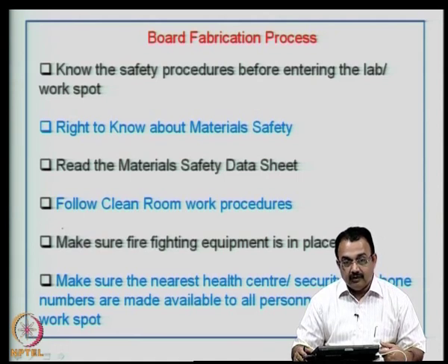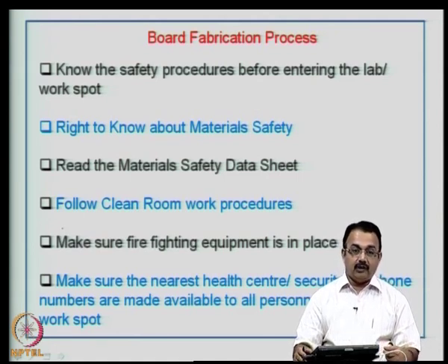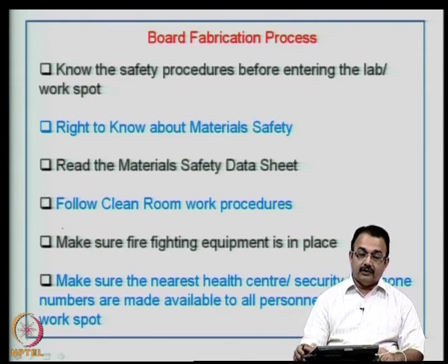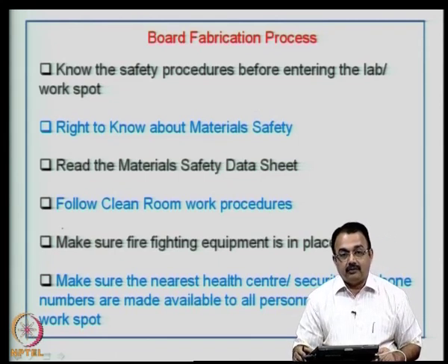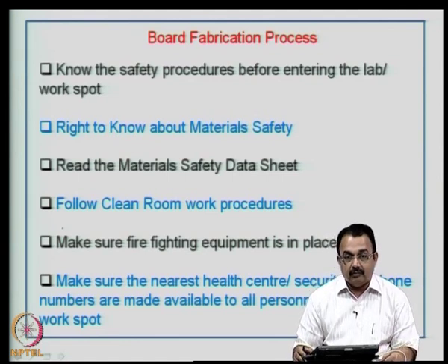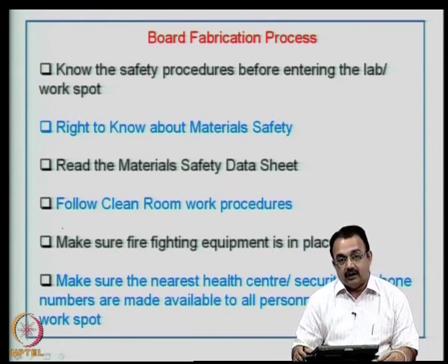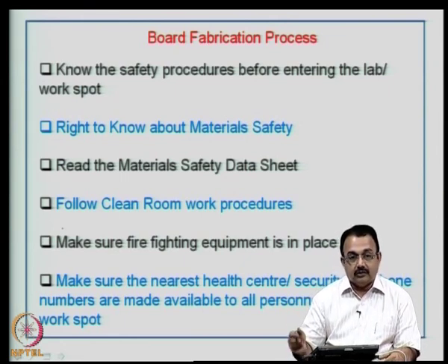Follow clean room work procedures. Clean room work procedures will again vary depending upon the classification of the clean room. We talked about clean room classifications when we talked about semiconductor manufacturing. It could be a class 10 clean room, class 100, class 1000, 10,000 and so on.